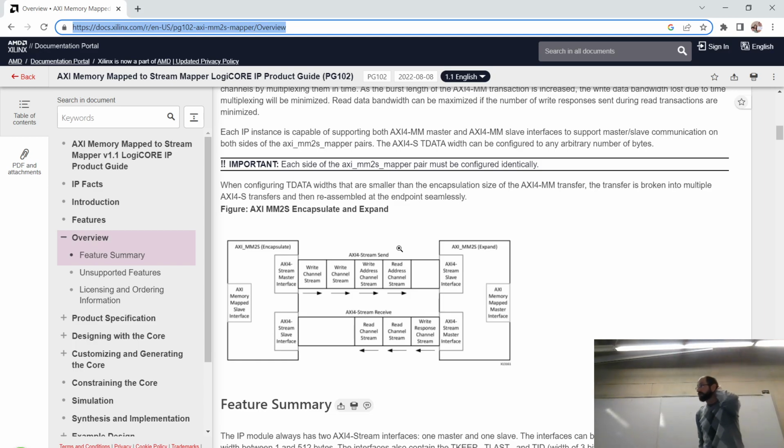And because it's all just going to ultimately be a memory mapped system, we specify in our driver, I want to send 32 bytes to location 10,000 hex in our system. The Ethernet core grabs those bytes at a time, connects them, tags them so that they're appropriate for this really weird model that we're interfacing with. This then allows us, via the Ethernet request, to send data anywhere we want in our system.